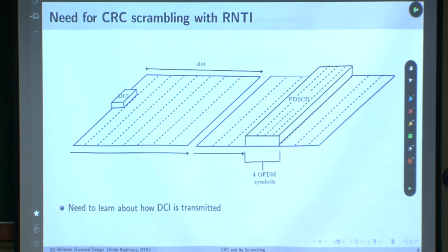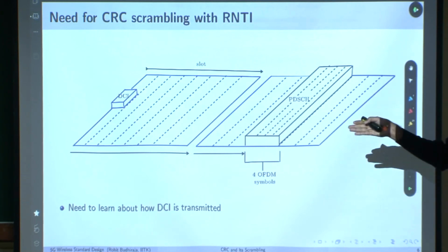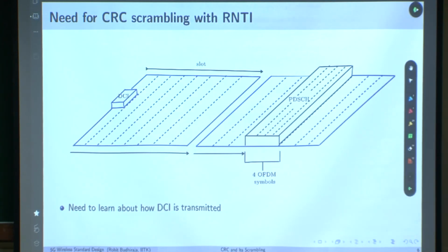So you understand the blind part? It is searching. I'll explain in detail how it searches, but it has to search, and that search is blind. So your mobile does that every time. Every 0.5 millisecond in 5G, it does the search unless and until it has been put into sleep mode by the network. So you understand the complexity of this.